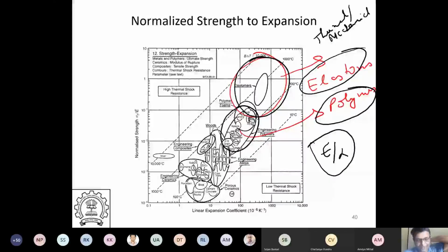But if you see all the gaskets, the pressure cooker gasket, these are all elastomers. So you'll have to use some of the materials which can withstand high temperature. Some of the O-ring materials have very high temperature withstanding capability. In some cases, Teflon is there, which also has reasonably high temperature capability. There are certain polymers and elastomers which can actually take high temperatures, but most of them cannot. Most of them cannot go beyond 200 to 300 degrees centigrade.